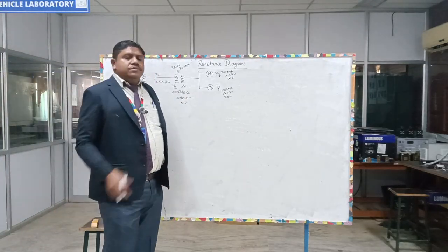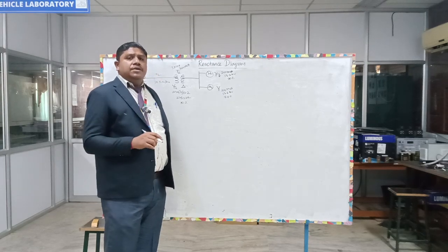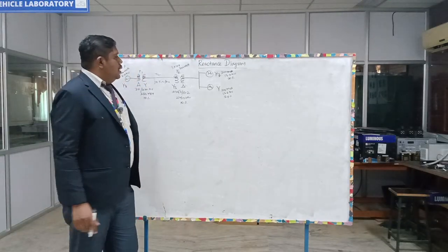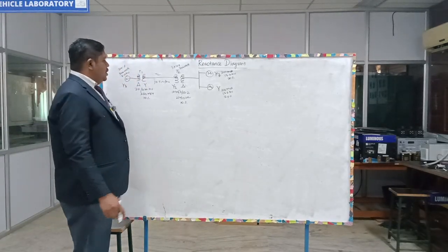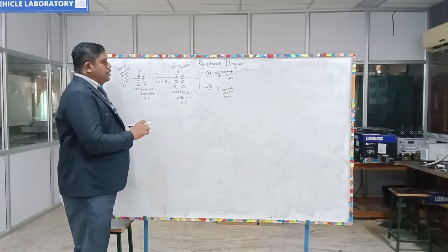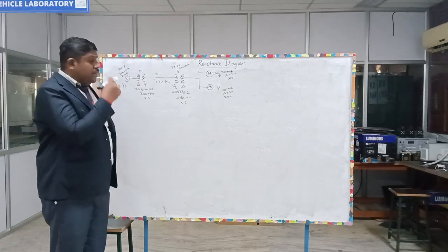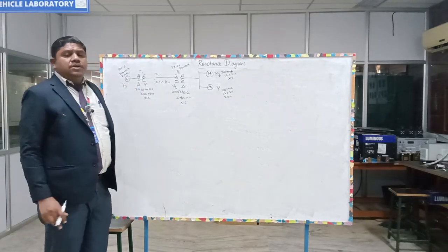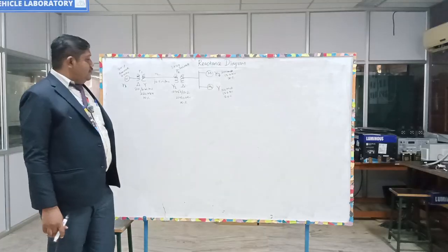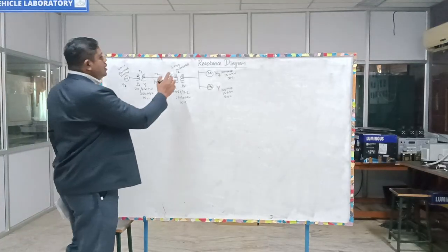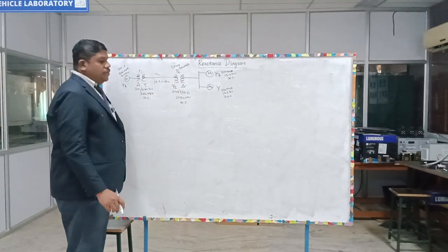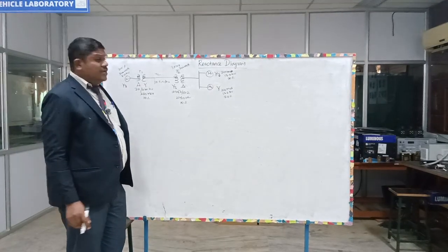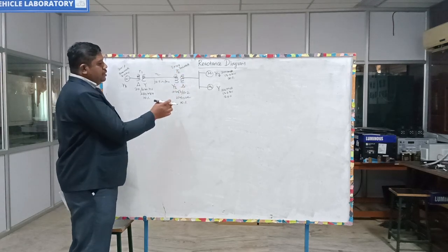So, next problem. For example, for the same reactance diagram calculation, if the transformer rating is given as three single-phase transformers, or it's given with star-delta connection or neutral grounding, how do we calculate the reactance diagram? Here, transformer T2 we are considering as three single-phase. The MVA is given as 100 MVA, so it is 3 into 100, 300 MVA.